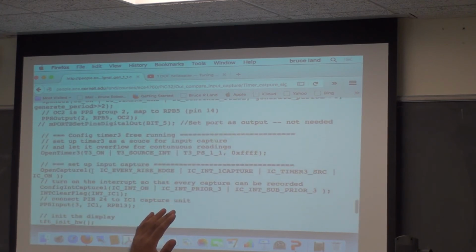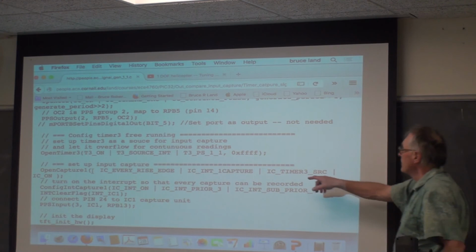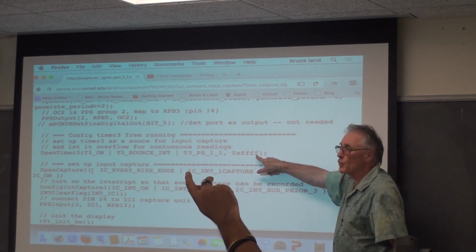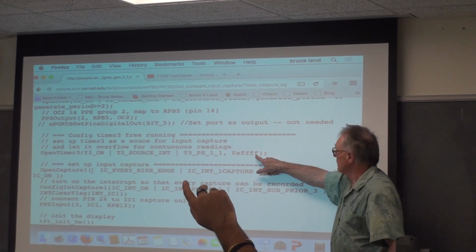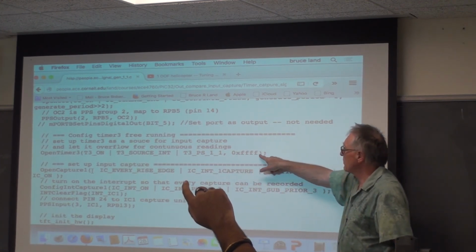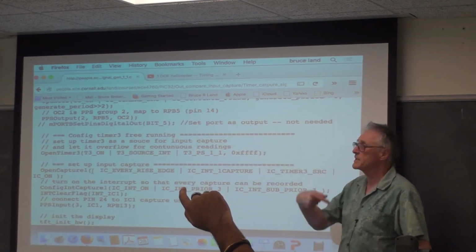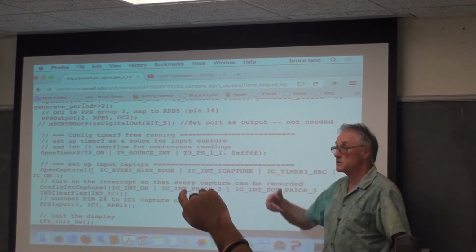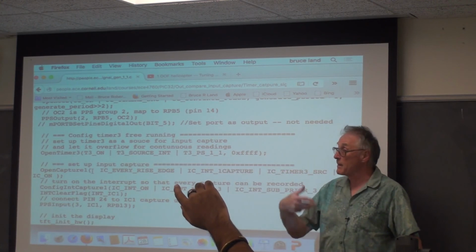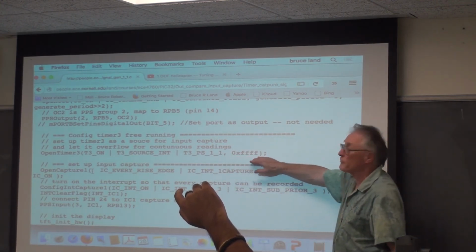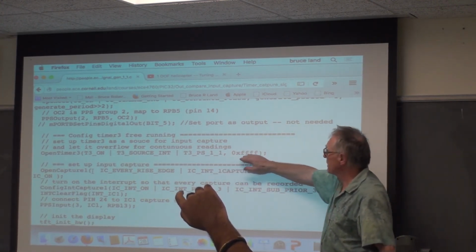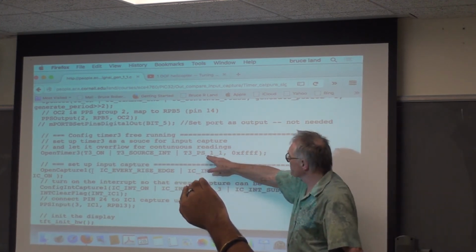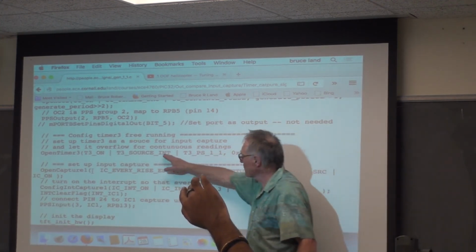What does it mean, free running? It means that the reset value is set to full scale. So the reset value at which the timer automatically resets to 0 is set to FFFF. 0 is the next logical count on a wraparound. So this is so-called free running. There is no particular timeout on this. Again, running at full speed with an internal source.